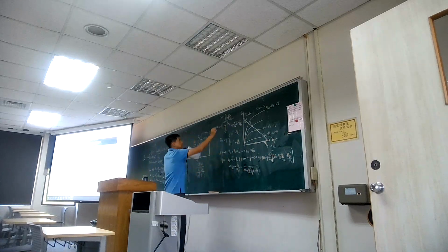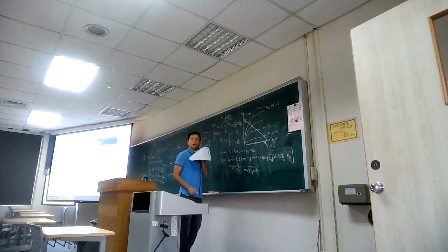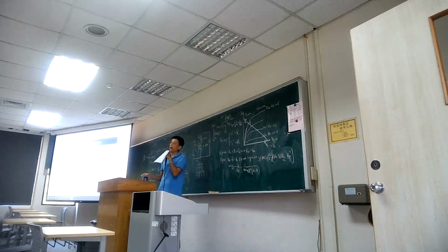Okay, so actually the output voltage can also be simplified since we get this equivalent circuit as RDS. Here is the VDD, here is the output Vout, here's the ground. So it's just like a voltage divider. We separate the voltage along this part. And since the RDS is typically small, we can consider most of the voltage drop is along RD. Typically it will be 7 kilo ohm, and this one determined by this value.